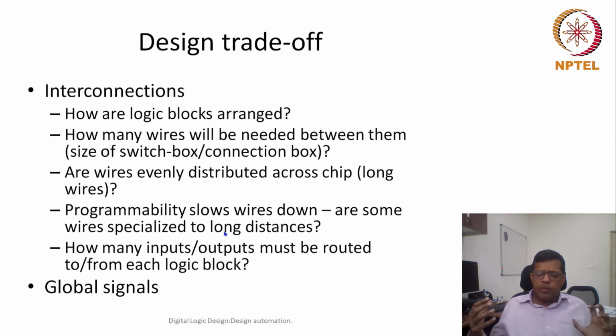So that's why we always think that if there are some connections which are more frequent, can we directly connect them, or can we make certain connections non-programmable? Non-programmability would always give a benefit in terms of latency or wire delays. Okay, so choosing which wire should be programmable and which wire should be non-programmable is a good question.